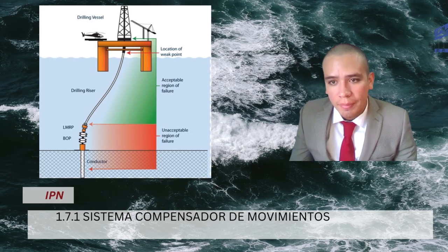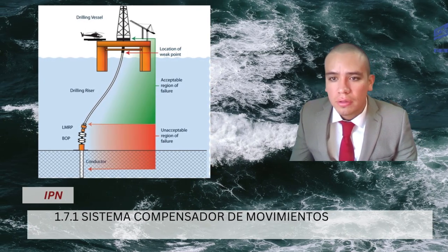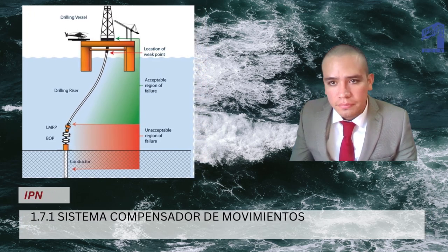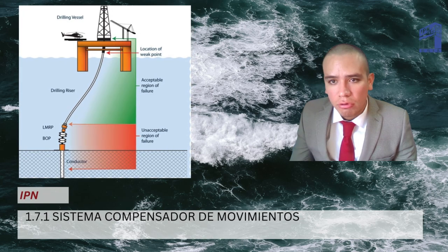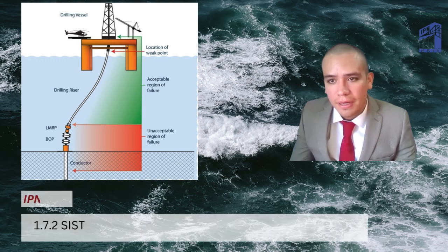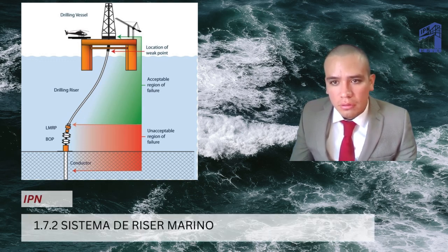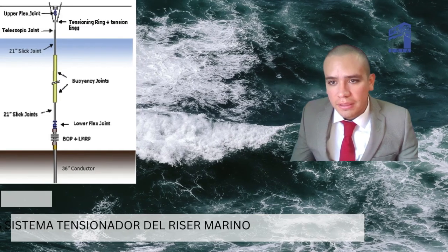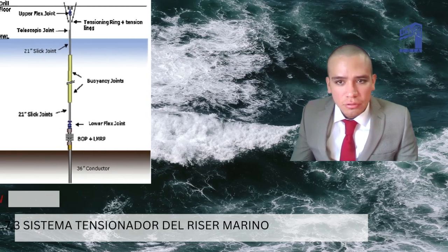These types of hangers serve the following functions: suspend production tubing and provide access to the bore and annulus, provide seal preparation and subsequent orientation of subsea trees, seal the annulus, provide communication between the surface and the subsurface safety valves and downhole instruments, provide a means of structural orientation for the hanger system of vertical subsea trees, metal to metal annular seal assembly, advanced metal to metal sealing system, types of seals, optional hanger system, permanent guide base.